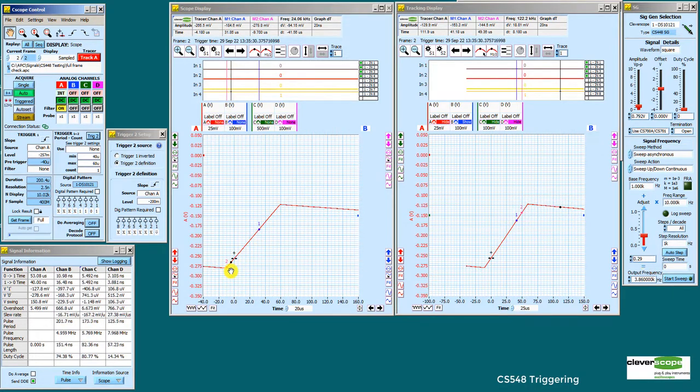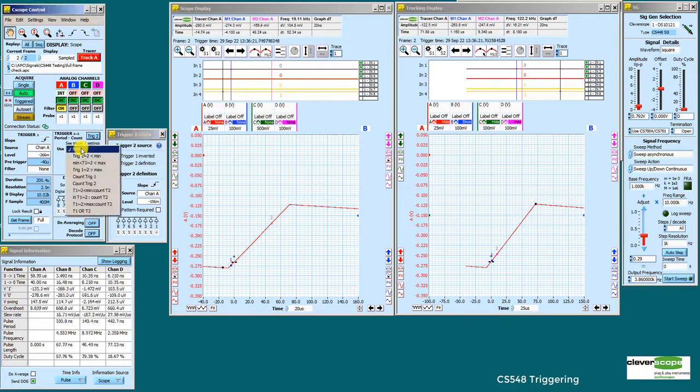Let's place a couple of markers that we're going to use to calculate our slope. So I've made marker 1 and it's minus 266 millivolts, and I can make channel A trigger 2 the marker 1 slope, which is minus 156. Now I can trigger just the same way as before, and I can trigger if at those amplitudes being shorter or longer than a particular period, we can trigger off it. So let's make this a range.